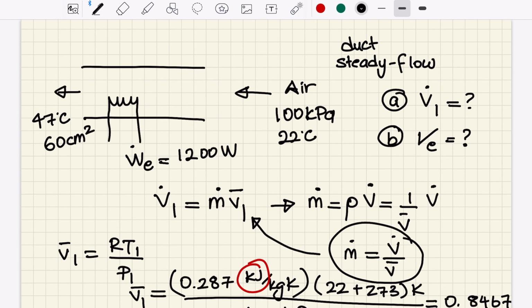All right. Now the question is, there is mass flow rate and we don't know the mass flow rate. The only way to find the mass flow rate here is if we actually write down the energy balance, because in the energy balance, mass flow rate term is there. And we cannot use any other equation because we are not given area, we are not given velocity at the inlet.